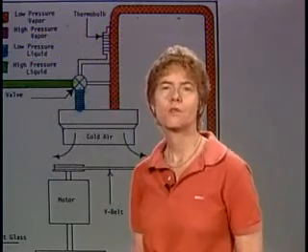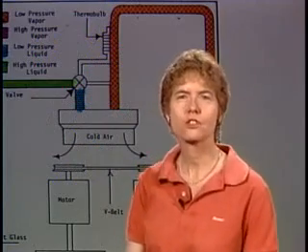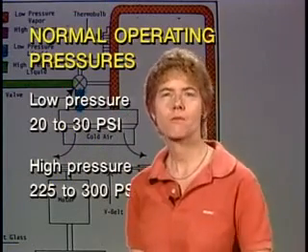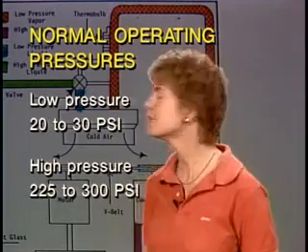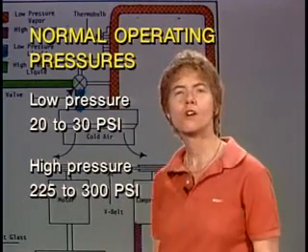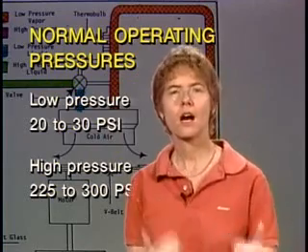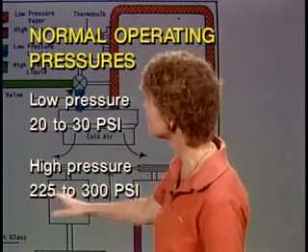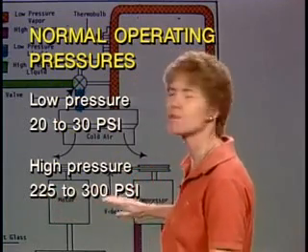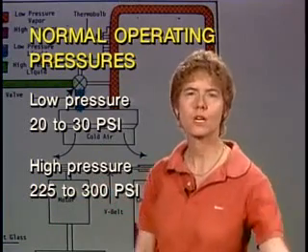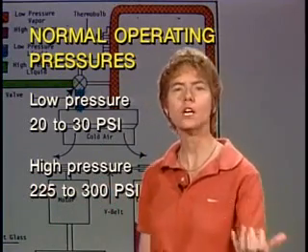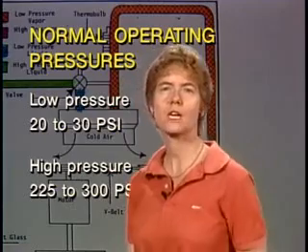The FAA will ask you what the normal operating pressures should be if the evaporator temperature is 40 to 50 degrees Fahrenheit. The low pressure should be about 20 to 30 psi, and the high pressure in the system should be about 225 to 300 psi. 20 to 30 psi low pressure, 225 to 300 psi for the high pressure.